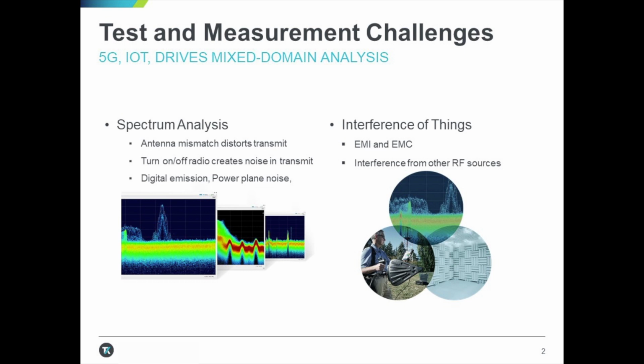You also need to check for digital control signaling errors, software integration problems, spurious emissions, and coexistence problems, especially in dense wireless environments such as hospitals. Thus, the need for mixed domain engineering analysis capability, including analog, digital, and RF, and being able to identify, classify, and locate interfering sources quickly is critical.